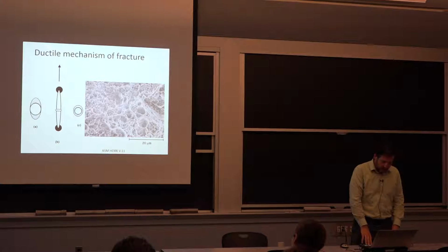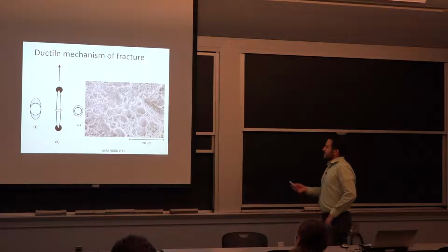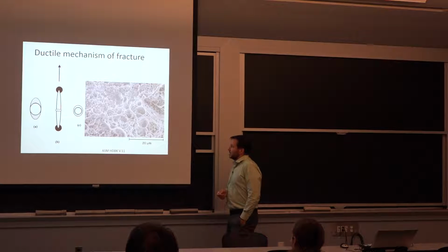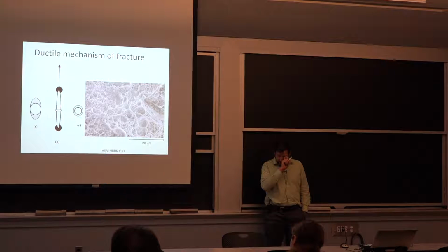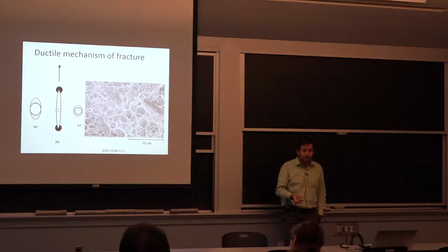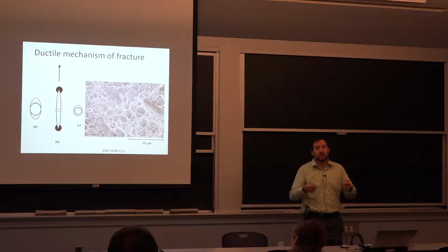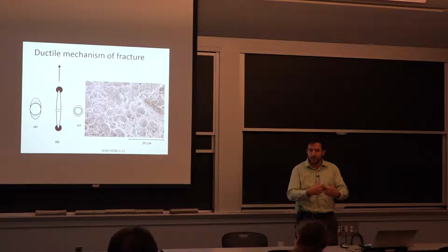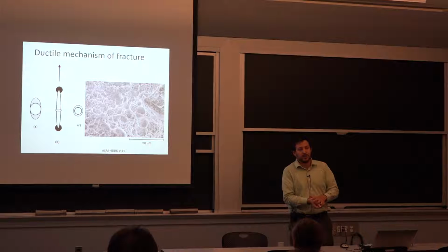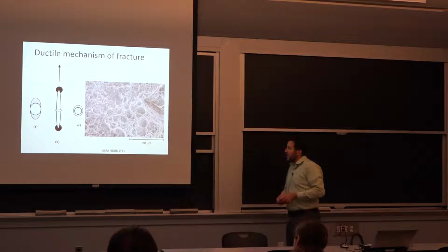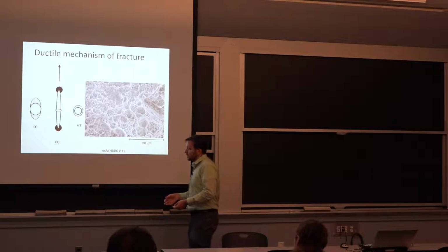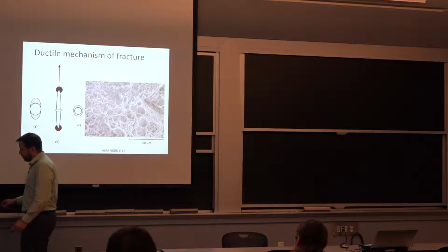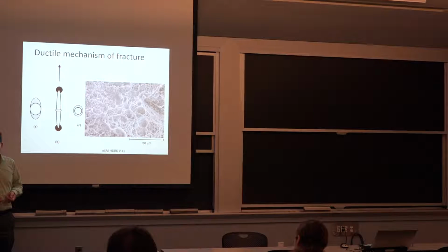One thing that we try to promote, this is something I brought in when we were talking about the deformation of metals. We were saying that, especially in forming, we try to avoid tension, because if we have tension, we tend to form these microvoids in the material. So all the rolling processes, the forging processes are intended to bring as much compression in the material as possible. So here we have the opposite case. Unfortunately, a lot of welds are loaded in tension, and to the extent that you're able to avoid any effect of the environment,